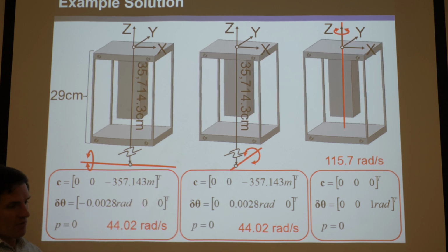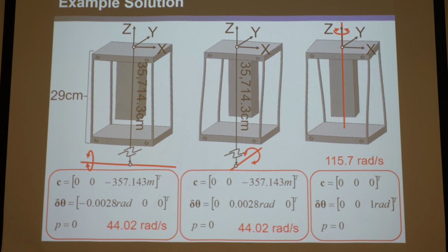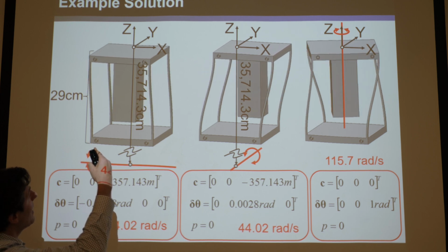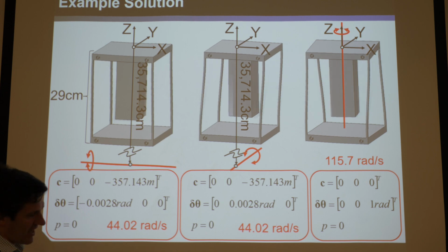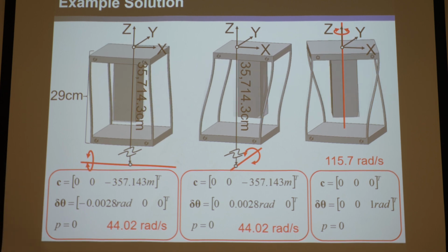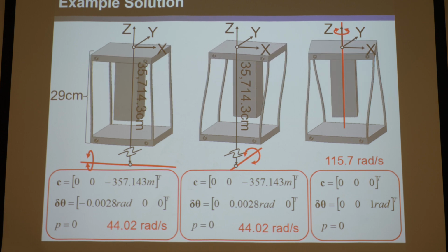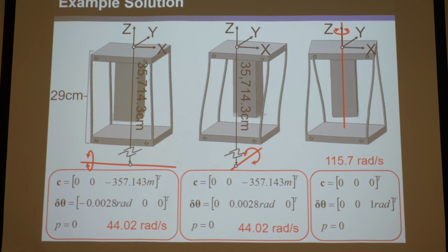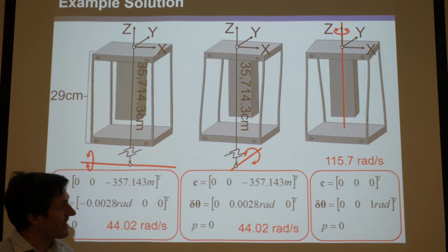Our system, when we calculate the mass and stiffness matrix, notice the system is perfectly symmetric about the xz plane and the zy plane. They're the same. You can rotate it 90 degrees, and it's perfectly symmetric. So, according to math, the analytical approach is not going to be able to tell the difference between those first mode shapes, and so of course they're going to be exactly identical.